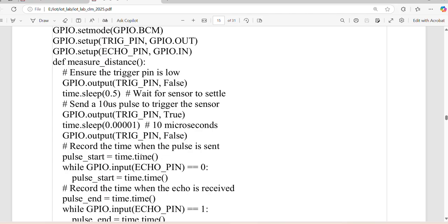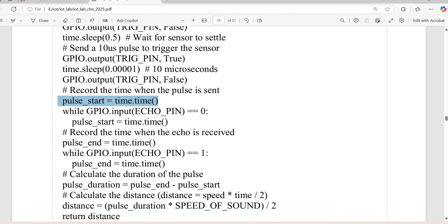Now after that, we record the time, which indicates the start time. As I said, the moment you send the 10 microsecond signal, the signal from the transmitter, the ultrasonic system, is going to be transmitted. So record exactly the time when the burst of signal has been transmitted, and here we wait. Are you receiving 0 here? So now let me assume that we have 1.